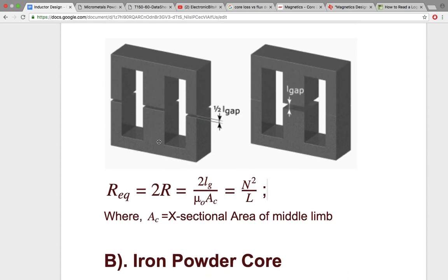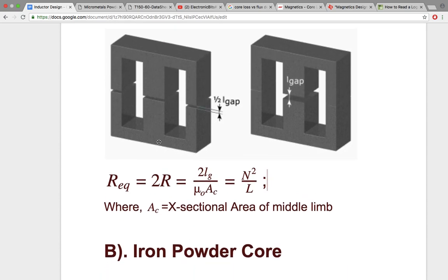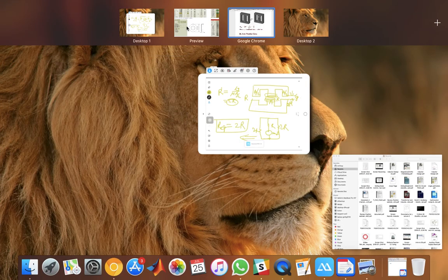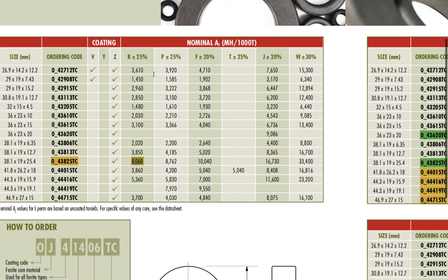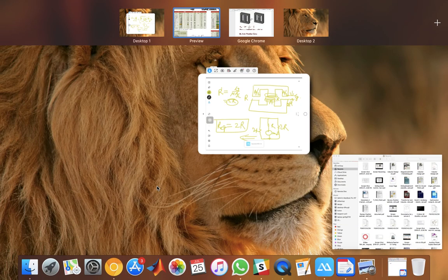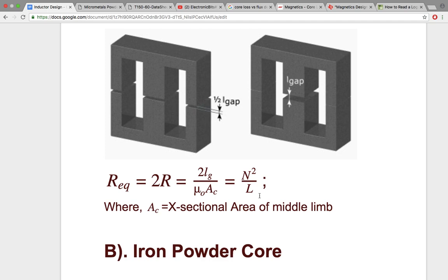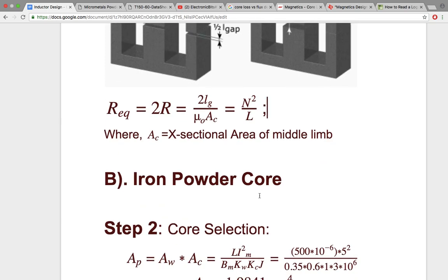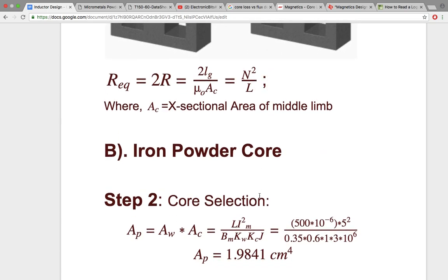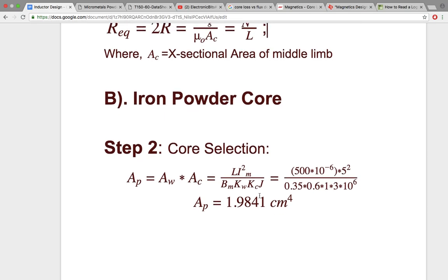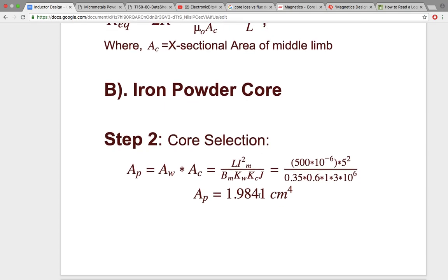Generally, for ferrite cores in high power applications, we don't use a toroidal core. If you have a distributed air gap, because of which we can have higher reluctance, then definitely we can use the toroidal ferrite core. Why I'm saying that: if you see the AL values, they are all pretty high. There is nowhere an AL value that is less. Because the AL value is high, the reluctance of the cores is less, and because of that we need some air gap for increasing the reluctance.